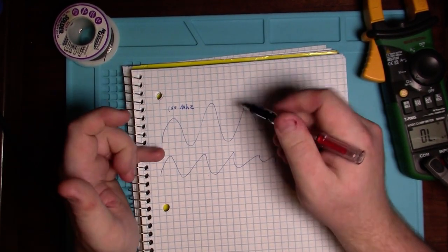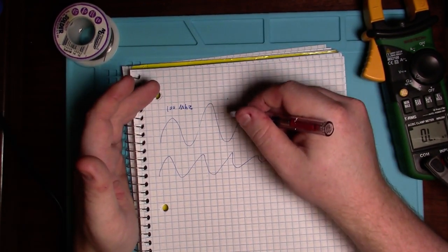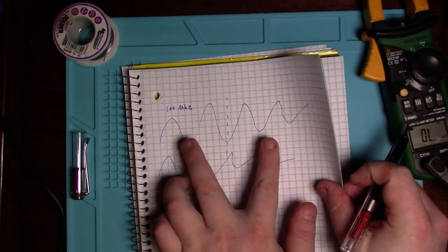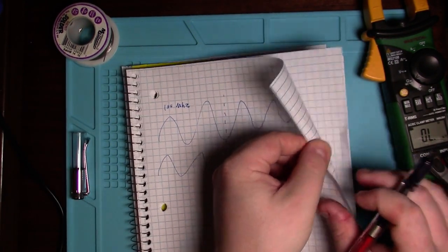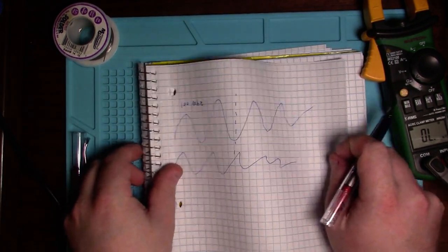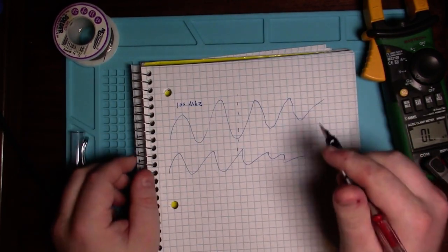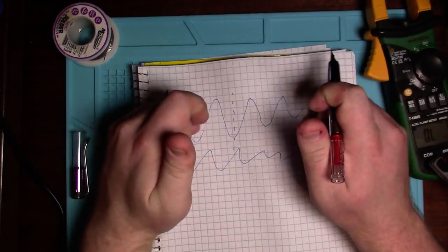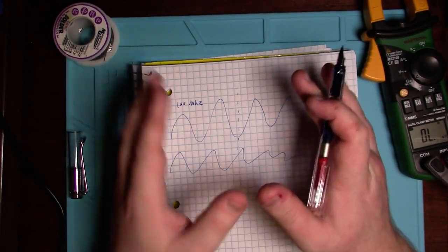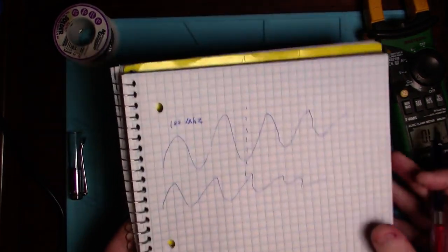And if we were to look at this on an oscilloscope, we would see a center line here at 100 megahertz, and the wave on either side of that line would do kind of a motion like that along with the audio. Right? So it's modulating this frequency. It's slightly changing it based on the information that it's carrying. And that's kind of it in a nutshell.